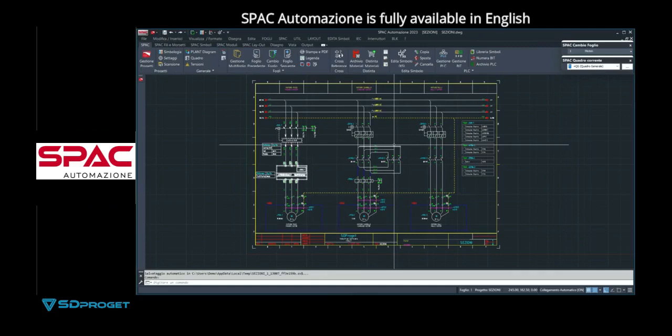If I then reinserted it into my current drawing that had already drawn the BLK, it would take the old block from me. This is because AutoCAD has a feature that inside the DWG saves all the history of the blocks, and so the block was taken from that library inside the drawing. This, however, caused a problem. If I modified and improved my block, completely changing it, the BLK1 became from a square to a rectangle, then a circle, I always saw the old block.